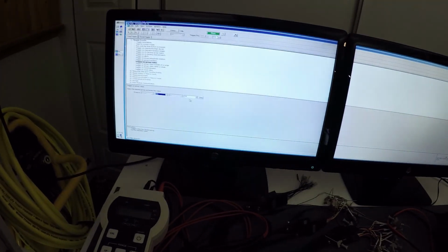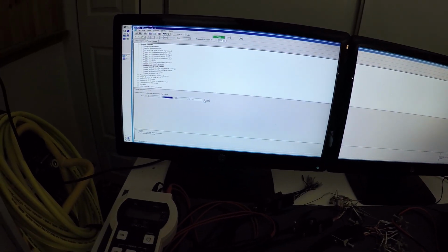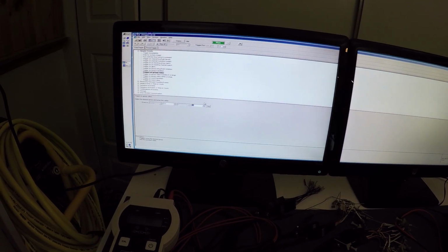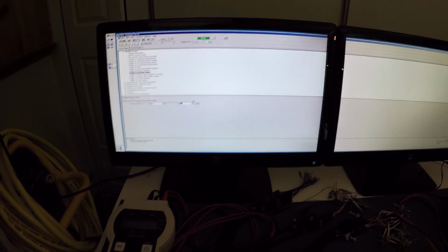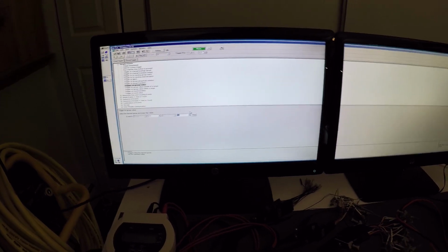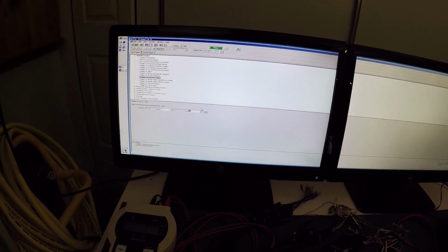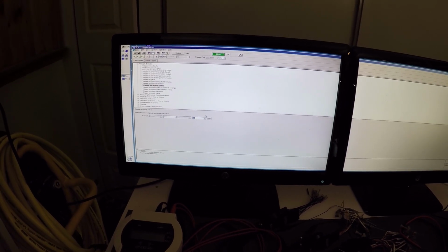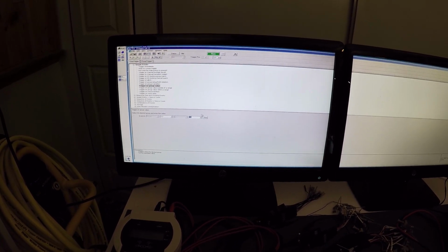And so I've set that up, and what I've done is I have it so that the trigger for this is going to be a hex value of 38 on the databus, which is essentially our first command, or our first value that we send on the databus as part of the initialization of the LCD display.